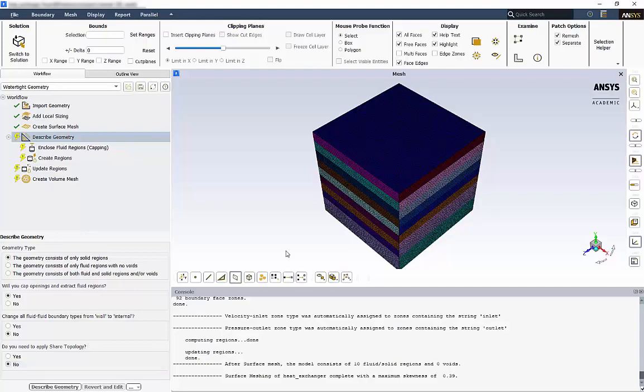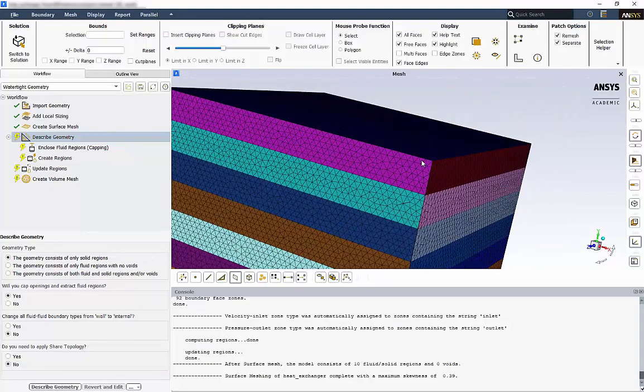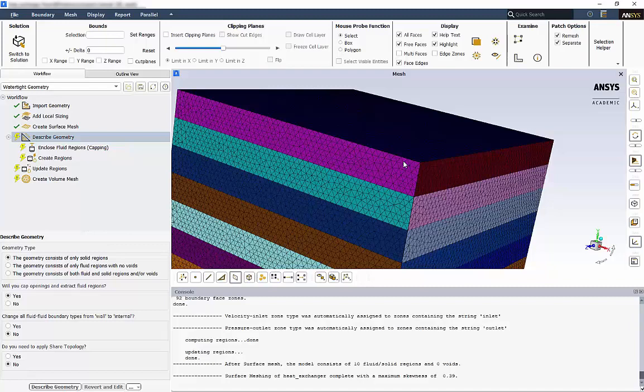We can already see here that our mesh size may be large. Because each subdomain of water and oil requires fine enough meshing, the overall mesh count may be in the hundreds of thousands. This will simply mean that the solution may take an appreciable amount of time to solve, but it would be quite difficult to generate a coarser mesh and still retain the relevant heat transfer effects.